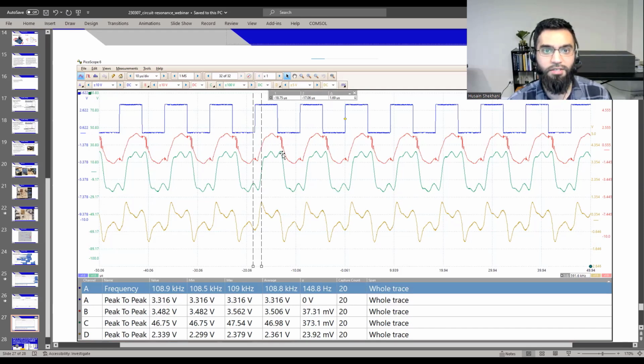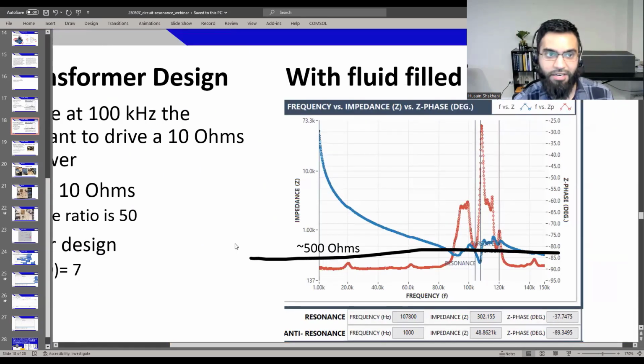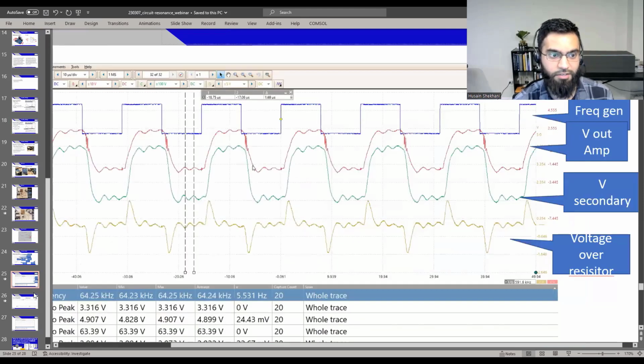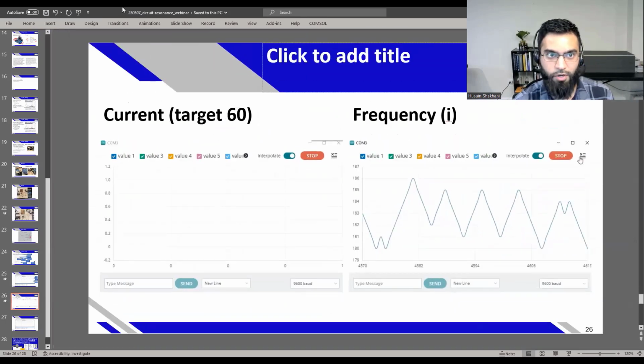And you can kind of see the input. The primary side is very similar to a sine wave in a way, but remember, your transducer reacts differently at different frequencies. Naturally, at high frequencies, there's lower impedance, so the current draw is going to be higher. Even if you have 1/10 of the voltage, you may still have a decent amount of current. And this transducer is not all that good at resonating in terms of the quality factor. It's not good or bad, but it's just not what perhaps many of us are used to in what transducers are.